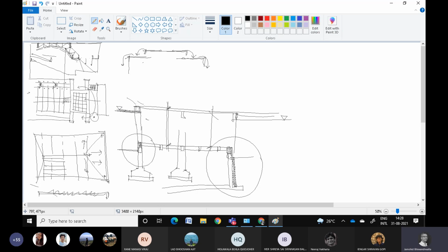So this is the level to which the column can afford to be concreted. That's why these beam bottom levels are usually given, giving you an idea to what level the column needs to be concreted, such that you don't need to break into the column, because breaking into concrete columns causes more damage than good. So my first level of dimensions is the floor to floor heights.